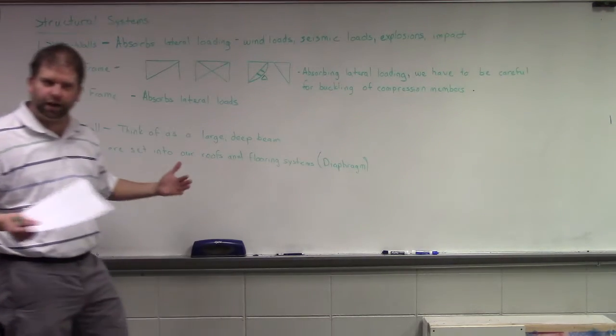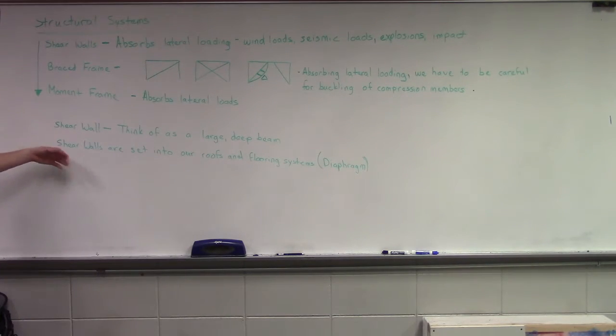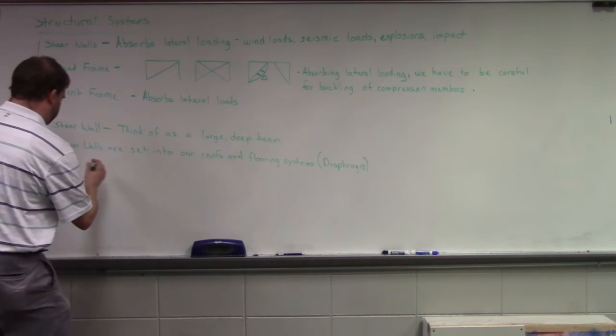It's going to transmit it into our shear wall, or if we're using brace frames, or if we're using moment frames. Okay, so that's how we're transmitting these things. Then the walls and the portions of the frames take up that load. They transmit it into our columns. The columns push it down into the foundations, push it into the earth. Okay, so this is all stuff that we've talked about in the past, not necessarily in this class up until this point, though. Okay, so we want to be mindful of controlling our ratios.